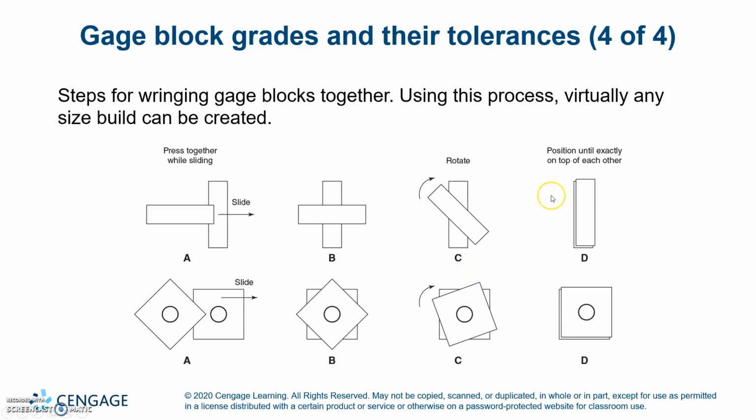What you are doing here is ringing all of the air out from between the two blocks. They're not magnetic, but if done correctly, they will actually stick together as if they are, because there's no air in between.